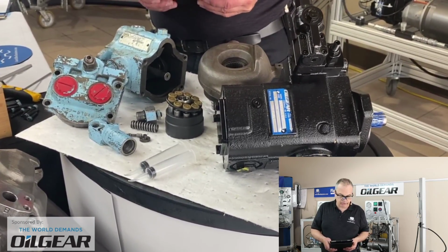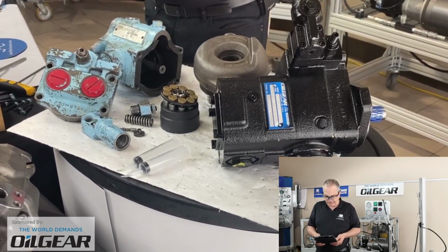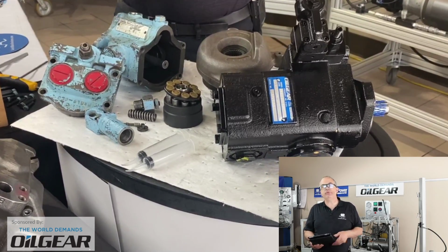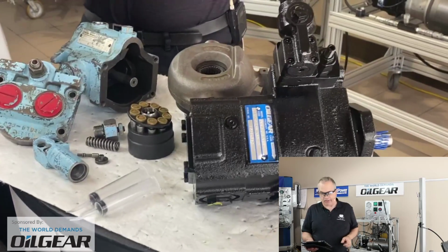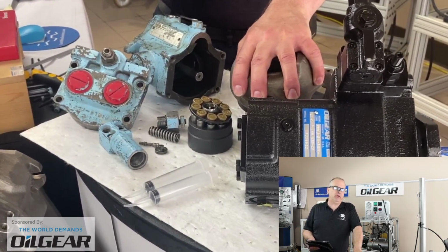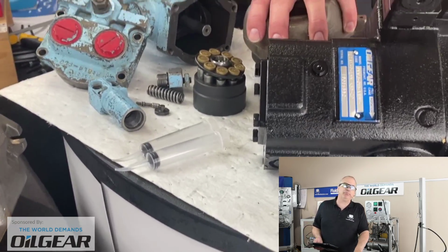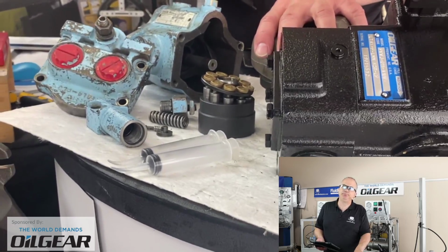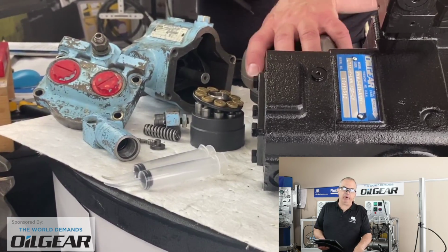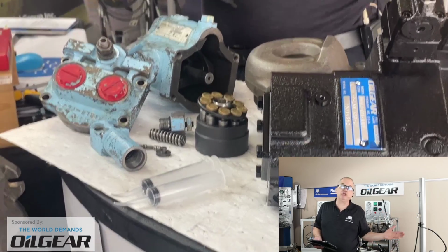Arnab asks about the pump not needing an unload valve. Let me think about that. An unload valve, yes, typically an unload valve, if I understand Arnab, is there to take all pressure out of the system, bring it down to very low standby. There's a number of ways to achieve that, even with piston pumps. It can be very advantageous if there is a long period of standby, over just letting even a pressure compensated pump be de-stroked but at high pressure.